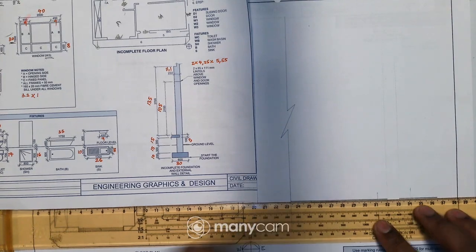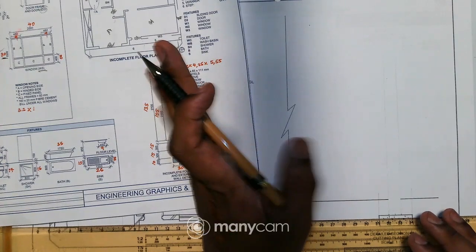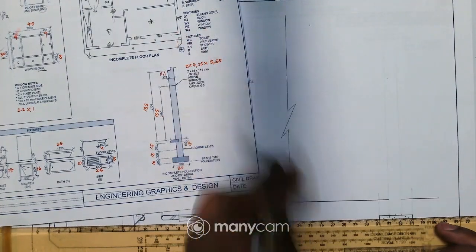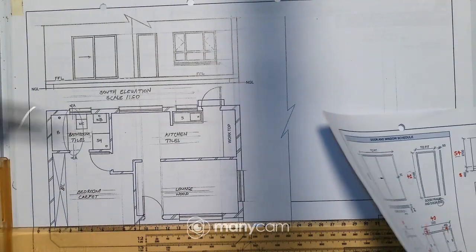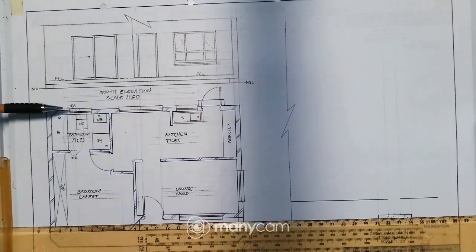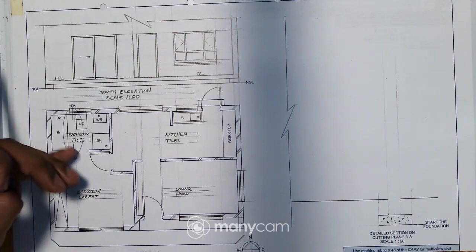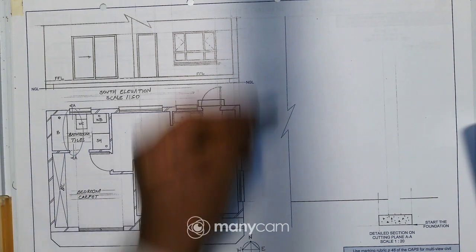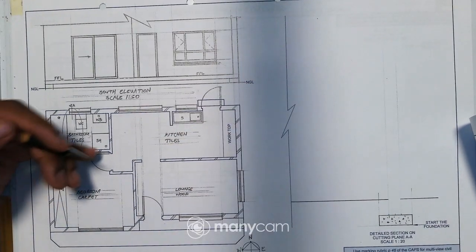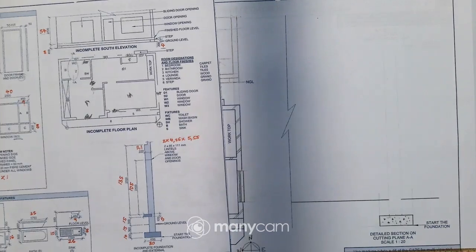So why do we have a break line? We have a break line to show that we still have something. This building is still continuing in this direction towards our left side. Why? Because if you look at our floor plan there, we are cutting only this part of the building, right? And remember, we still have a building all the way going down, right? So obviously we have to add a break line to show that the building is still continuing, right? Okay, I hope you understand that part.